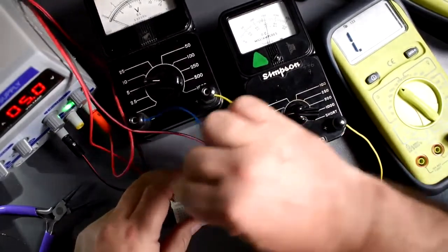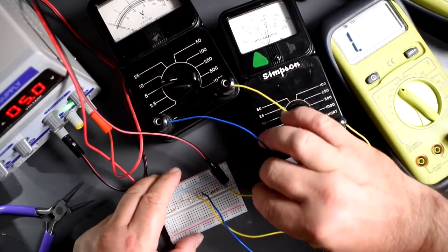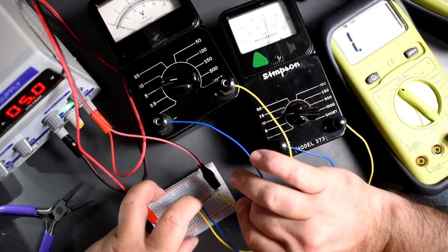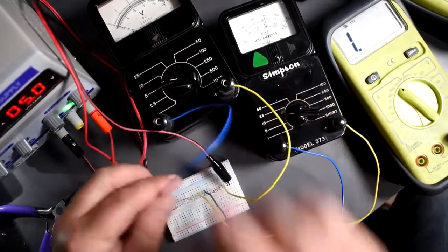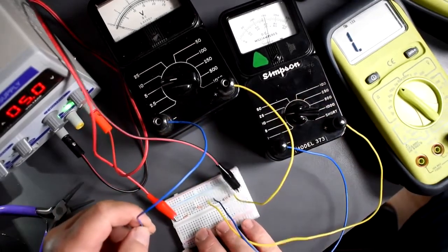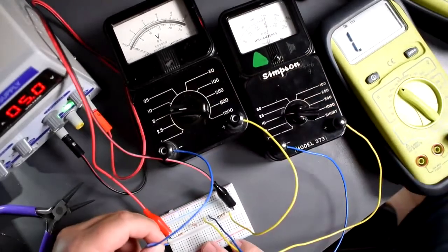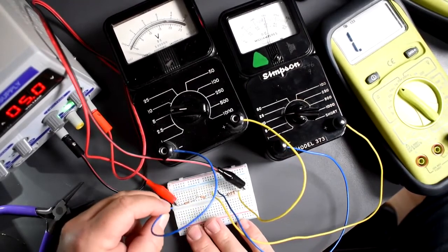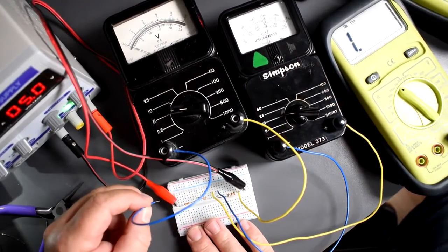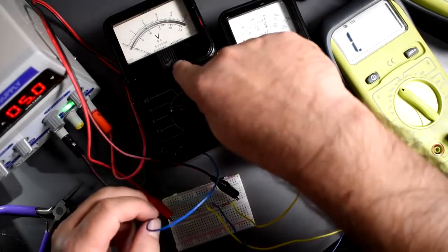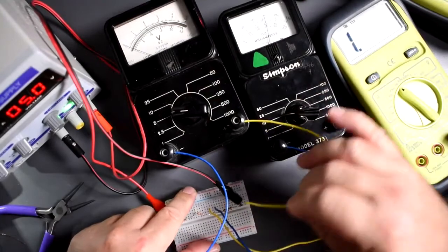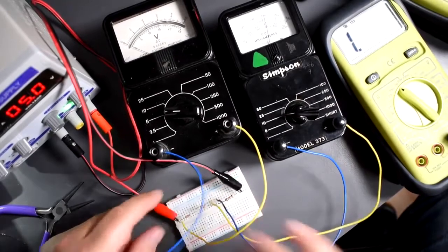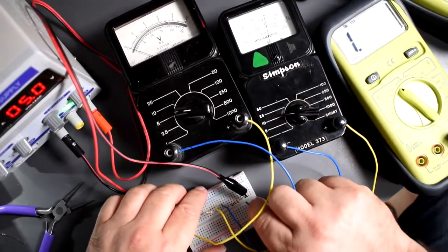Look what would happen if I reverse the polarity on, let's see here, that's where it goes. If I reverse the polarity on the analog meter, I'm just going to touch it briefly. The needle tries to go the other way. And if I held it for a longer period of time, then I would just burn down the element right here. So polarity is important while using analog meters. Okay, this one goes here. This one goes right across the power supply.